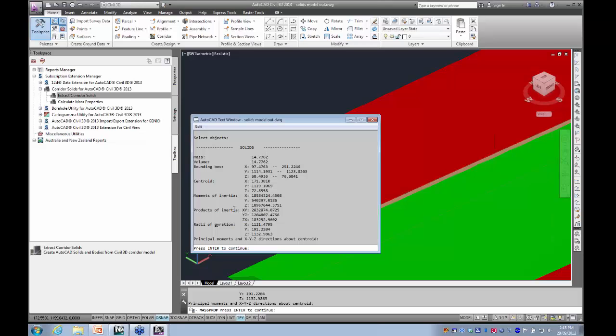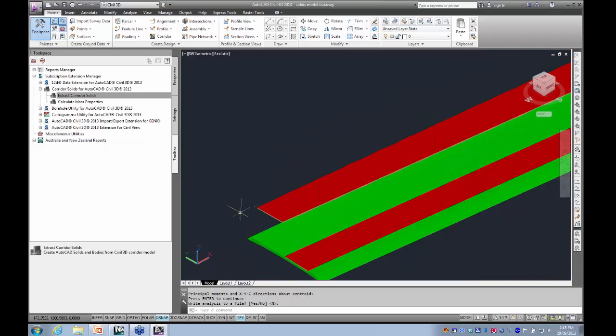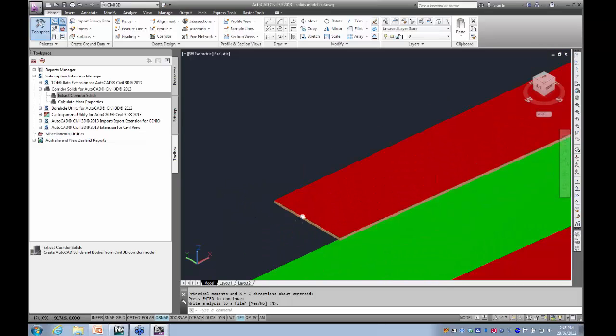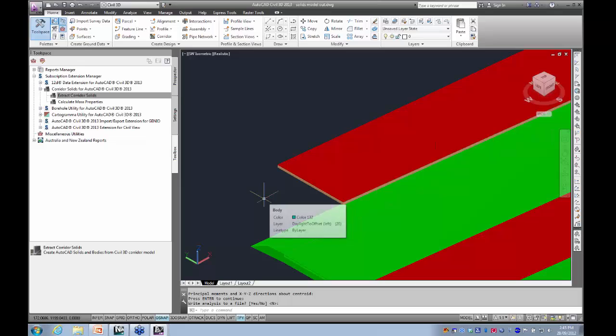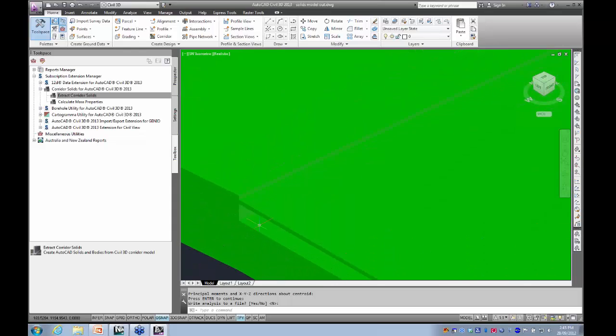So if you're not wanting to work out the volumes of your corridor chainage by chainage, we're just interested in certain regions one at a time, that would be a fast way to extract, if you like, the solids without having to do a complete volume extraction in Civil3D, which can be a bit time consuming.